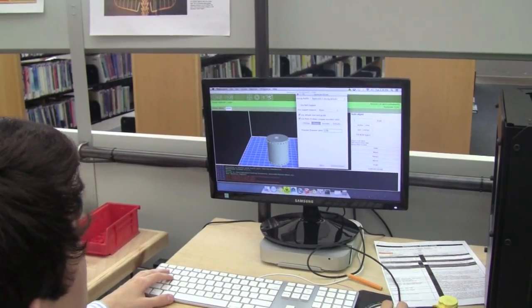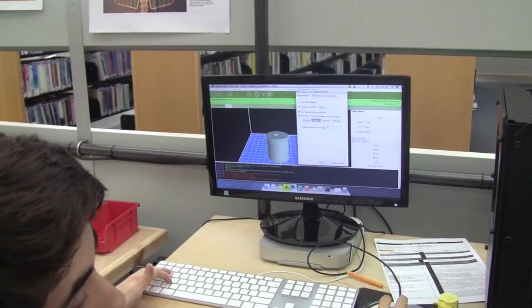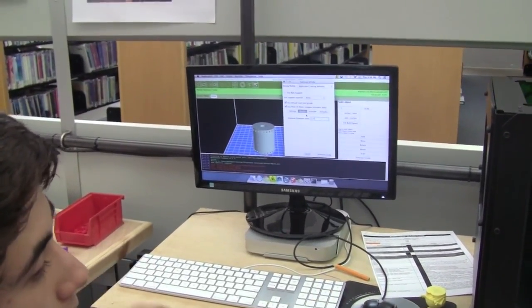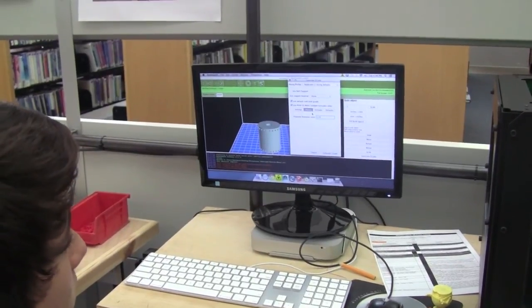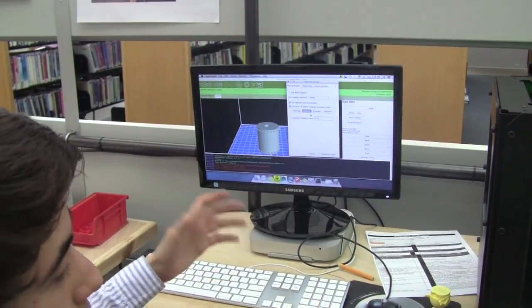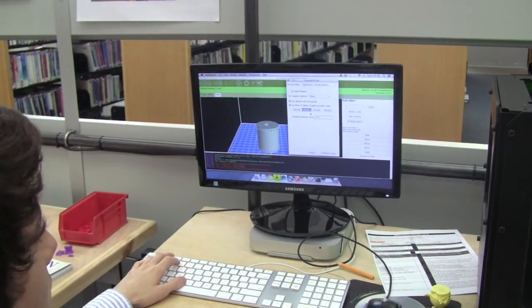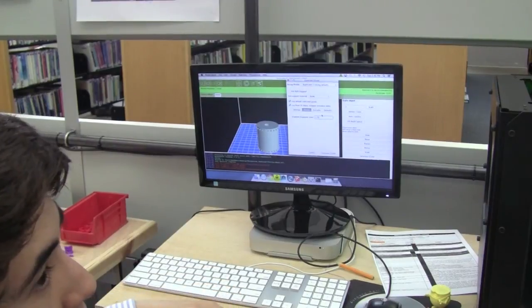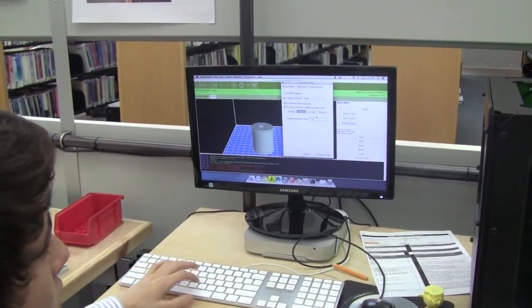Next is filament diameter. So we have varying diameters of the filaments. Depending on whether it's PLA or ABS, some of them are 1.8 or 1.75 millimeters in diameter. So you just want to change it according to the thickness of the filament. Normally it's really important when you have 3 millimeter filaments versus 1.8, because some of those do exist.